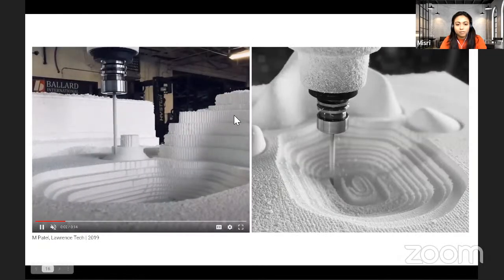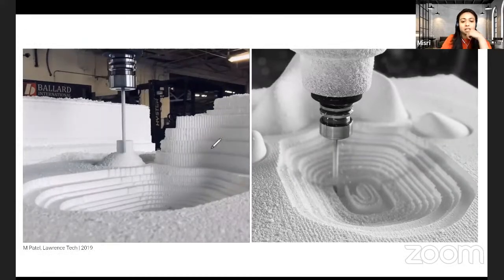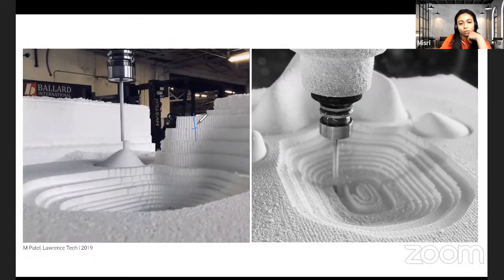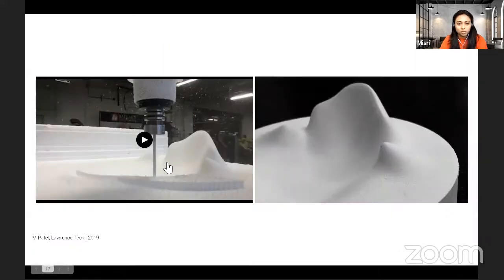So you start with a lot of roughing toolpaths, which are actually spaced differently. So with a material like this, and this is not something we'll be getting into a lot of detail, but it's just good to know that when you do roughing passes, you can really space them out to like 1 to 2 inches if your material is as soft as foam, and really make the lines closer as you go up so that it gives you high resolution. So the image on the right is actually the end product, which is a really smooth geometry and looks fairly close to its Rhino counterpart.